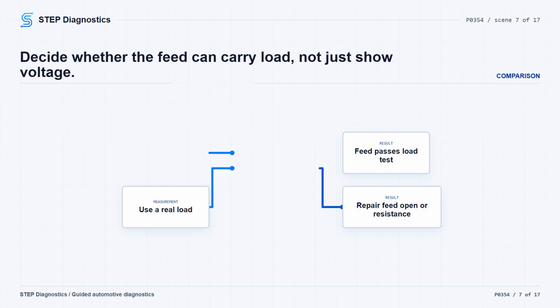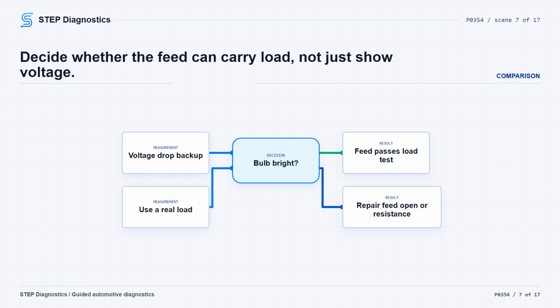If a test light is being used as the load tool, make sure it can actually load the circuit. A high impedance light that draws less than 0.1 amps is not reliable for this load test. The tool should draw more than approximately 0.75 amps. You can also use a voltage drop check across the 3156 bulb to be more certain the circuit is good.